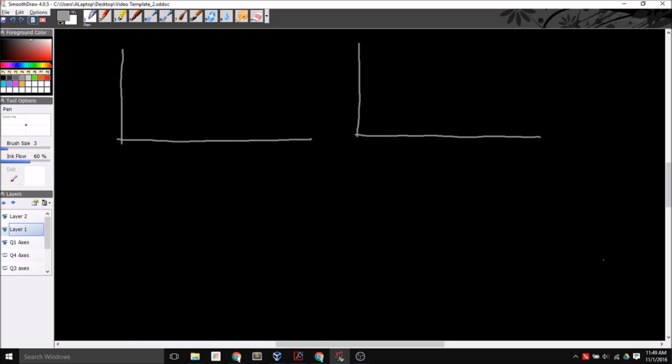So with digital, either something is completely on or completely off. That means it's either connected to, in our case, since our Arduinos are 0 volts or 5 volts. When we were dealing with our LEDs, if I wanted to turn an LED off, I would say digitalWrite, then tell it the pin the LED is on, and then say digitalWrite pin whatever, LOW. And when I say that, what I'm really saying is connect pin 13, for instance, to 0 volts. So have 0 volts on that pin, and the LED shouldn't turn on.